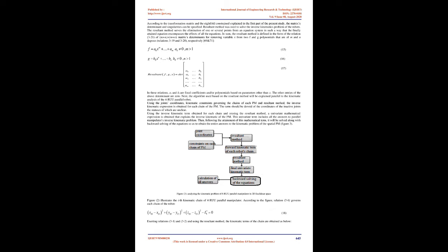To obtain the point coordinates of Ci, the transmission matrix takes the following form based on Eulerian matrices 6 and 8. In these matrices, the parameters of the robot's coordinates of root are x0, x1, x2, x3, y0, y1, y2, and y3. In fact, these parameters map the displacement vector in movement space through the transformation matrix to the point in the reference coordinates. To simplify the algebraic variables, there is a need to make a variable change based on half of the angle, θ/2, about which joints rotate.